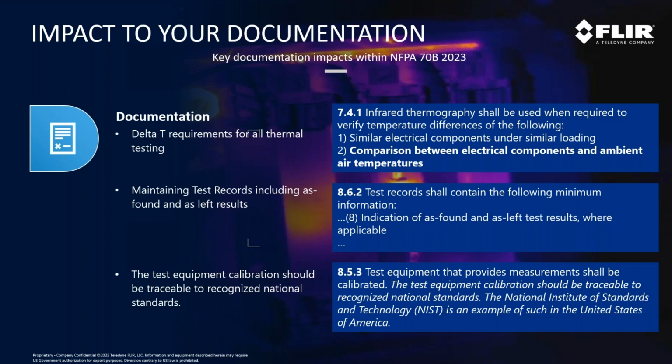Understanding full well that the time of day that you take those images, the load that the asset is under, are all going to play into any sort of comparative analysis. But basically, you need to prove out that you've gone through all of your electrical equipment and done the documentation properly. And that gets us into the next section here, the maintaining of test records, including as found and as left results.